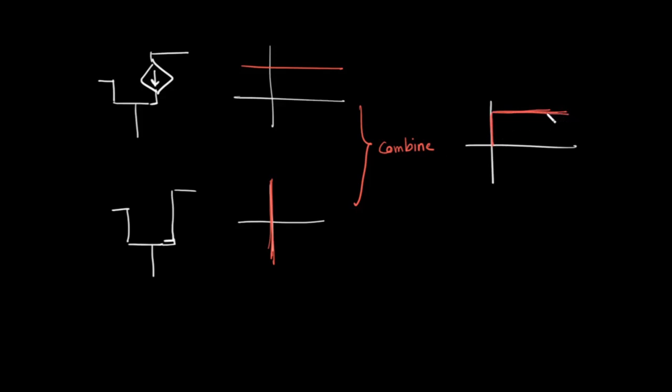Okay, and interestingly, this is the same IV characteristics of a MOSFET as well. So this is IC versus VCE. For an ideal MOSFET, if we draw the IV characteristics, the output current will be ID, the drain current, and the output voltage will be VDS. That will be exactly like that of the BJT.